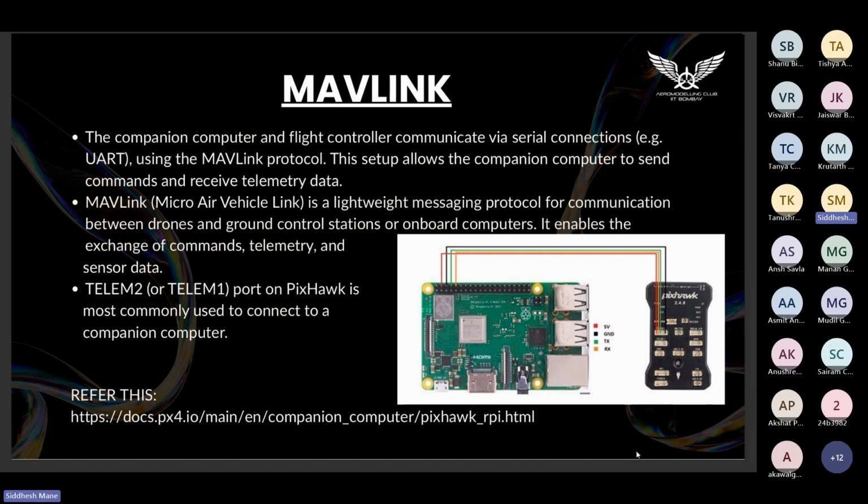In order to connect the flight computer to the flight controller, we use a telemetry port. For connections, you can refer to this link. This is a documentation where you can find how to connect your Pixhawk to a flight computer. You can see here, this is a Raspberry Pi, and it's connected to the telemetry port of Pixhawk, right?